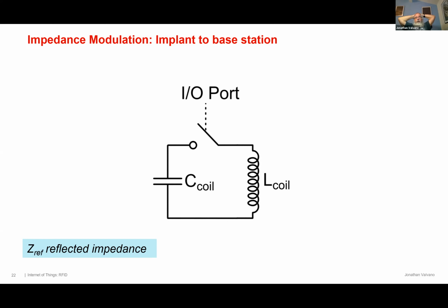So basically all we did was, our uplink communication was a GPIO pin, which was, again, modulated. Of course, we did it at 10 hertz because we knew nothing. And we basically detuned the coil one way or another, basically setting up the capacitance we added to the secondary coil to be two different values.